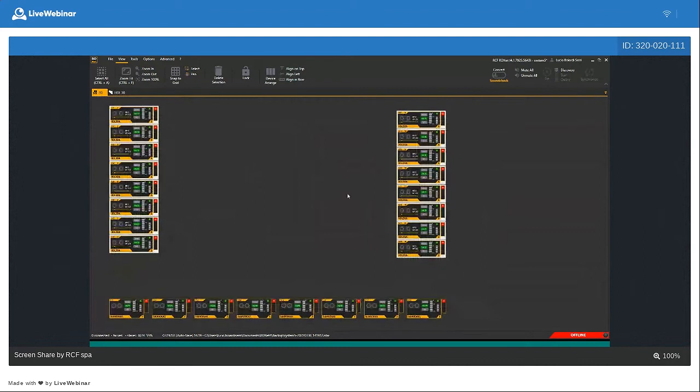So select the clusters, and then first of all we have to assign these clusters to an array group, because they are line arrays. Right click in some place. Once both the clusters are selected, we can right click and then assign to array.